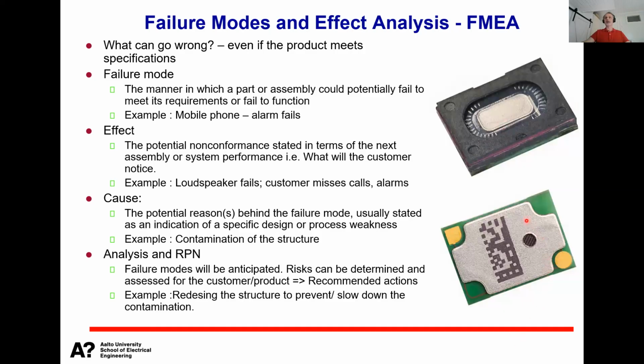And that is typically done so that you have a hole there somewhere. It's quite often underneath the component, like here. So when the clock should start to ring, there's a membrane inside which starts to vibrate the air, and then the sound should come out from here. If this hole is blocked because of contamination, then the sound is weaker, and then you might miss it.